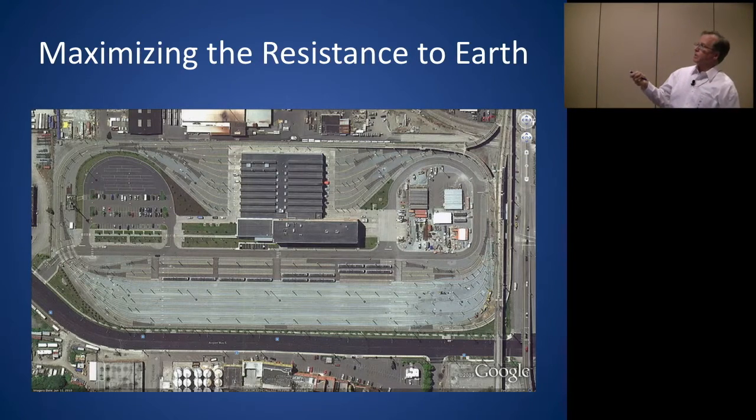And again, this has like a 5 or 10 mile an hour speed limit in here, so it's not real high. They're not trains accelerating, so it's a pretty low load. But we want to keep that separate from the main line, which has all the train activity and everything on it. So we separate that. It's called segregation. That helps us to maintain the resistance.